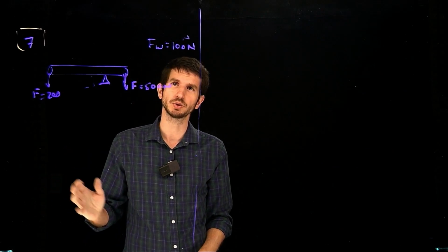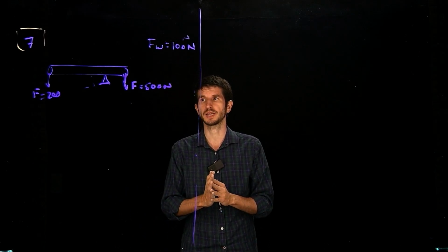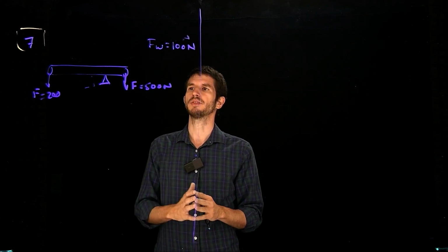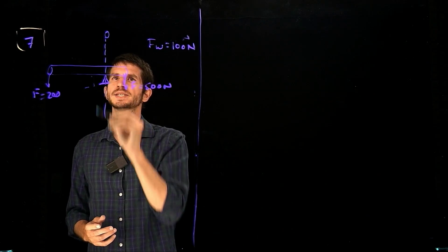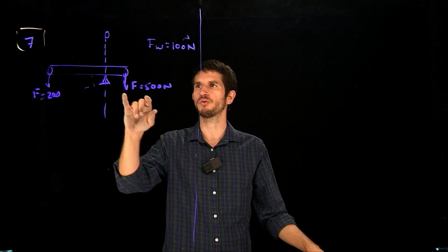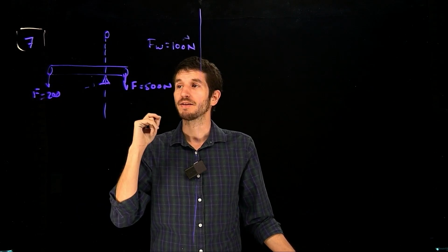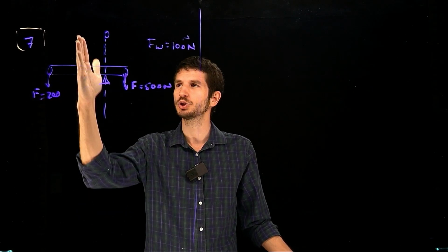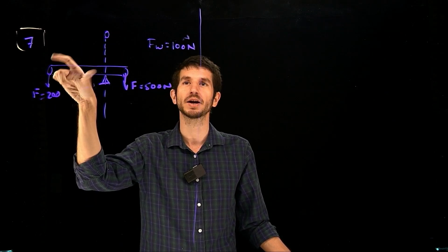A very important thing to realize is that the origin of coordinates we choose is irrelevant. We can take anything to be 0, which in this case we're probably going to take to be this point. And why is that irrelevant? Because if the balance of forces is 0 here, it's going to be 0 in any other one too. Why? If it were not 0, if I choose another axis where this one is 0 and that one is not, the thing would start rotating about that one.